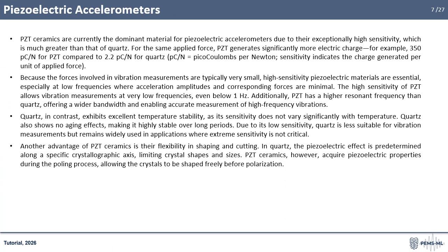PZT ceramics are the dominant material in piezoelectric accelerometers because of their very high sensitivity, which is much greater than that of quartz. For the same applied force, PZT generates significantly more electric charge. Since vibration-related forces are usually very small, especially at low frequencies, high sensitivity is essential. This allows PZT-based accelerometers to measure vibrations even below 1 Hz.